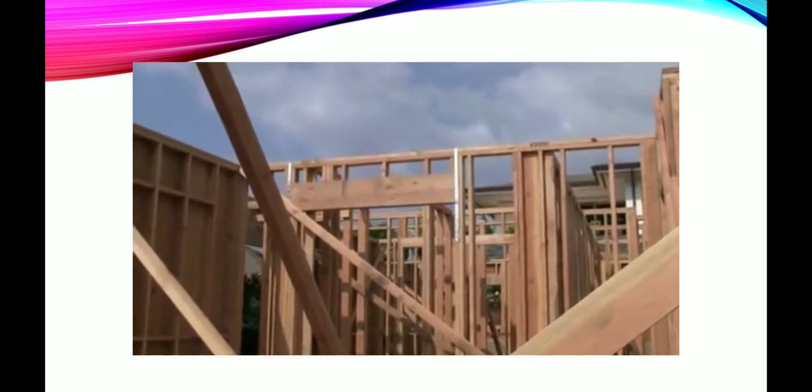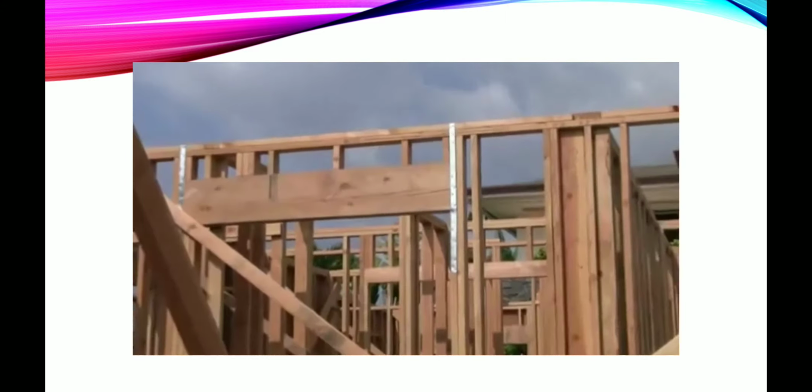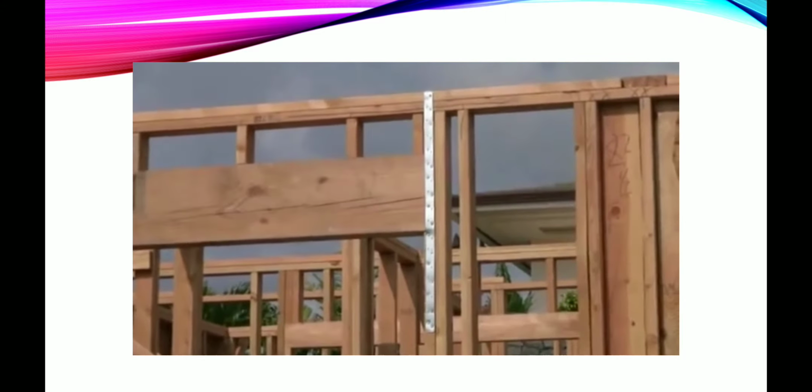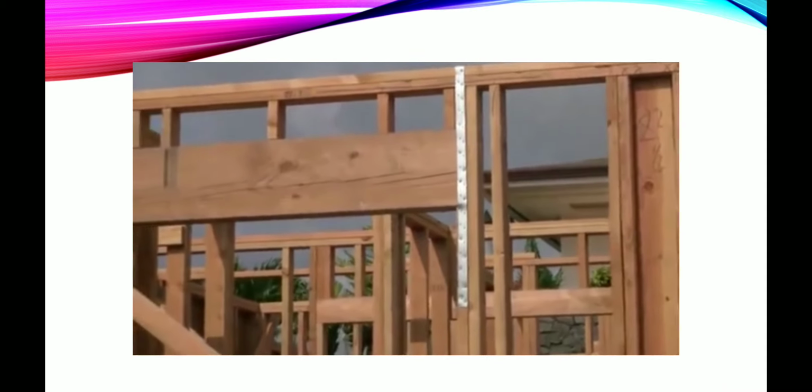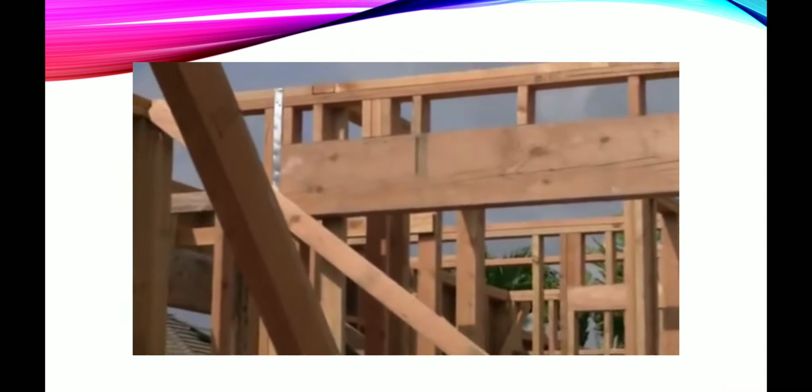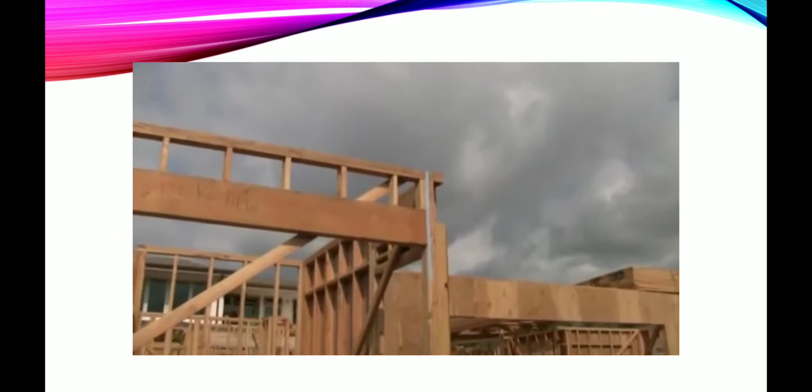In the old days, there were just a couple nails holding these together. The metal straps used here tie the top of the wall together. So when high wind speeds apply pressure to this home, we want the house to be tied together from the foundation to the roof to hold all of these different components together.